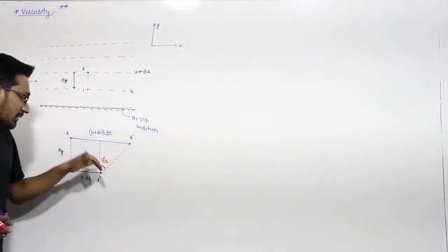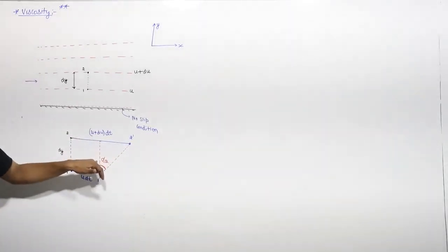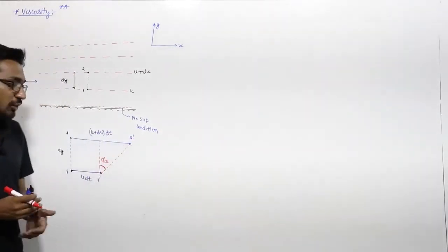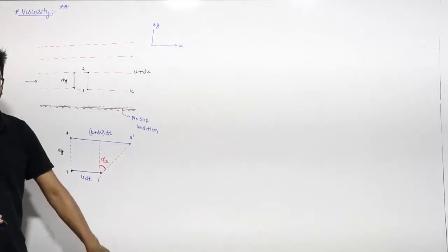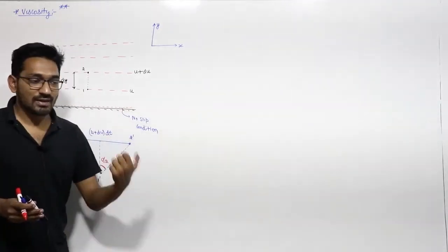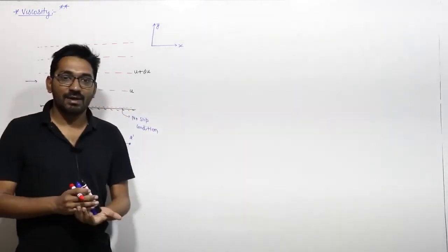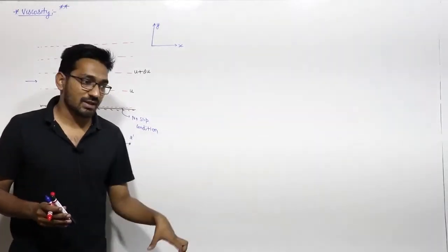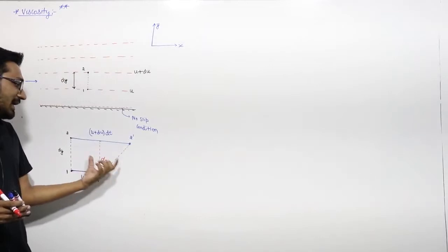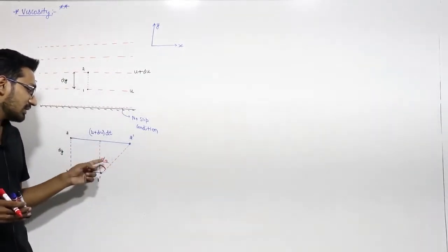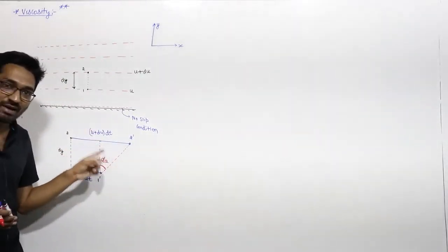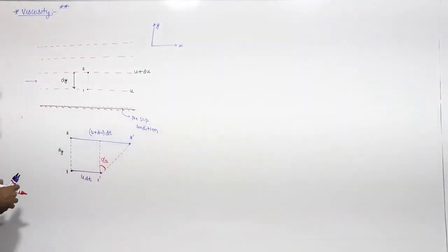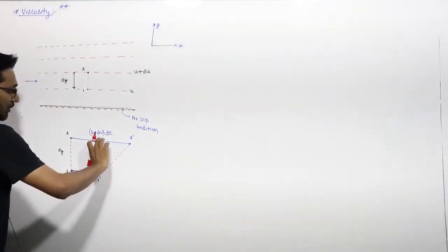As time is increasing, this angular deformation will continuously increase, right? And hence we say that the angular deformation in the case of fluid, when it is subjected to a shear force, is a function of time. That is not the case in solid. In the case of solid, that angular deformation or the shear strain is constant, right? But in the fluid case, the shear angle or this angular deformation is a function of time.